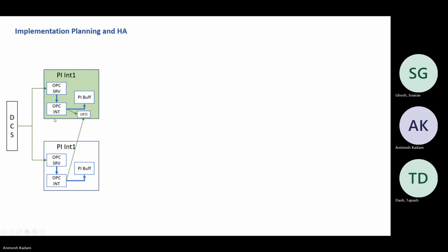and sending data to the PI server. To do that, we configure UniInt failover, which is a type of configuration that creates a file on one of the systems. So it's your call where you want to keep this UniInt failover file. You don't keep it on both systems; you keep it on any one of them. And this failover information will be stored inside this file.